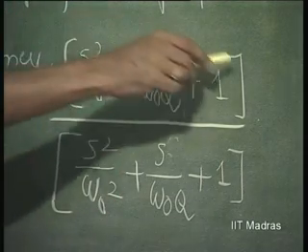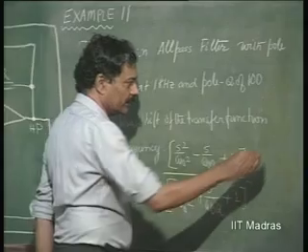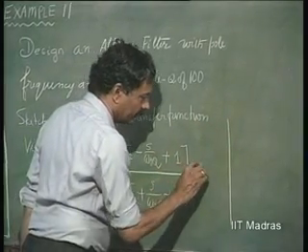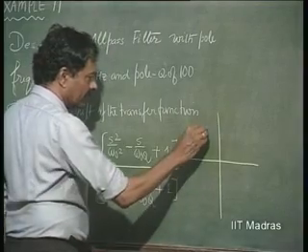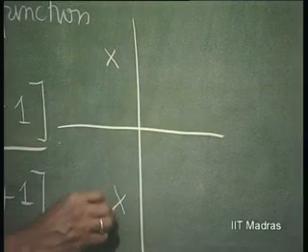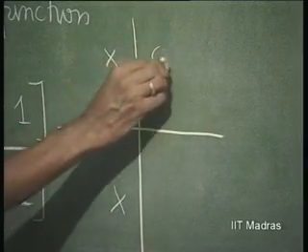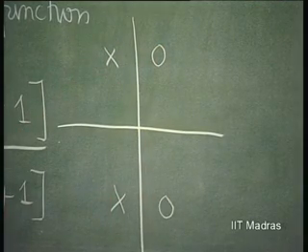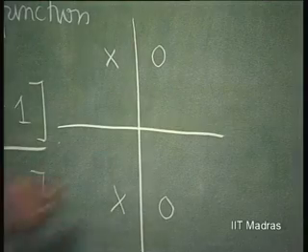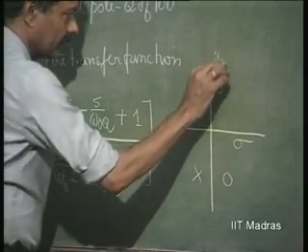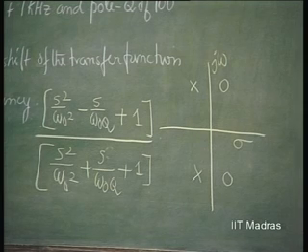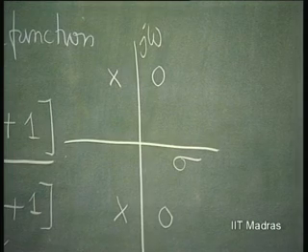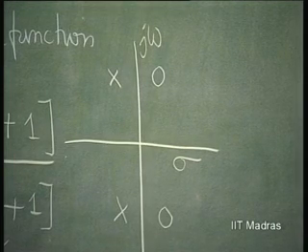These are therefore the zeros. If you plot these zeros actually in the S domain for an all pass, you will see that there will be a complex conjugate pair of poles if the Q is high, and there will be a pair of zeros, mirror image of poles. Okay. So, this is going to be in S domain the location of poles and zeros for an all pass transfer function. What it is going to be used for is first something that we will discuss.